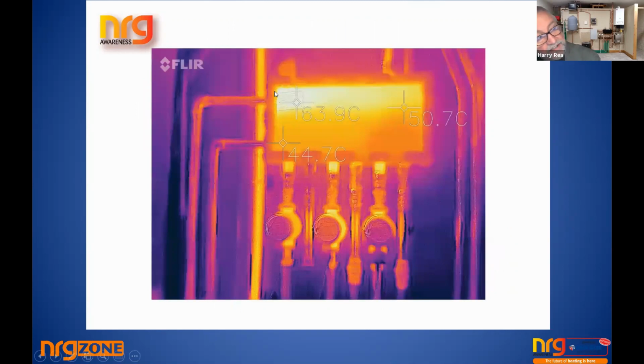So in a thermal imaging situation, you can see if heat is coming in from a boiler. Just suppose you have a gas boiler or something, and you have 63 degrees coming in. In this situation, you can see that the cold is reaching back up to here. That's a giveaway there's something wrong with the flow, because you've got cold water arriving back up here. So by adjusting the boiler pump, you now have the flow rate right, and you can set your pumps just by fingertip. Of course, you should have some kind of a thermal gauge to see what's going on.